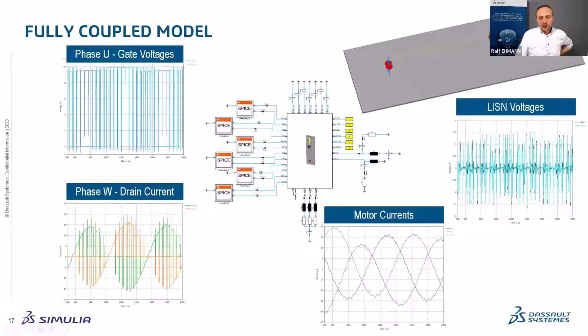So here you can see now the black box with the added circuitry. I know that SPICE veterans tend to be confused by the circuitry because it looks like everything is connected to ground. But there's a good explanation, and this just comes from the fact that we are using ports, and ports work slightly differently on the schematic. I can't go into too many details of this, but if you contact CST support, they can give you a great explanation on how this works.